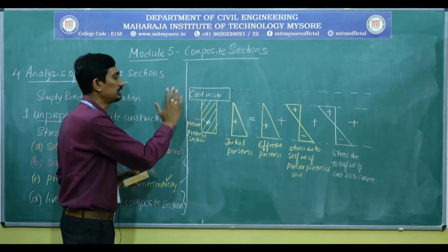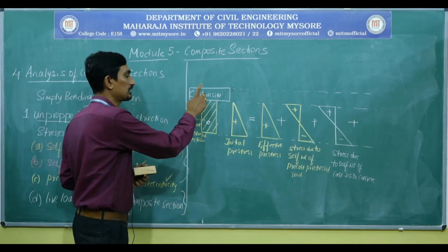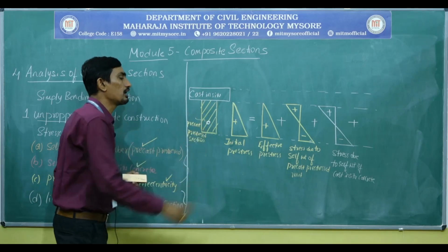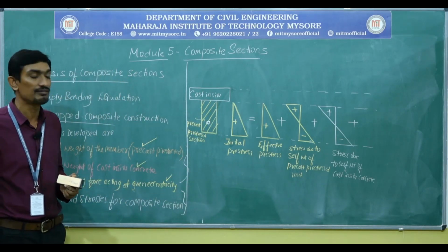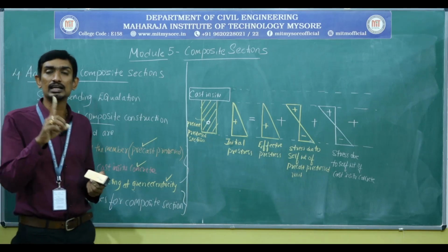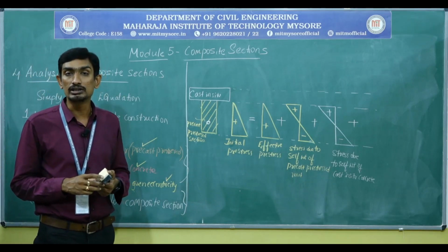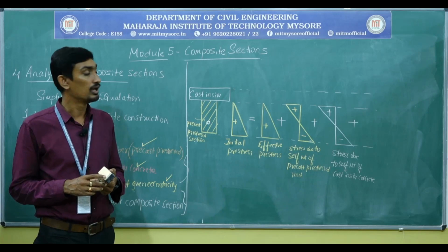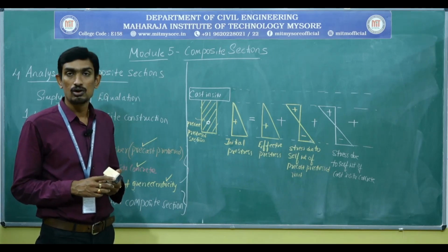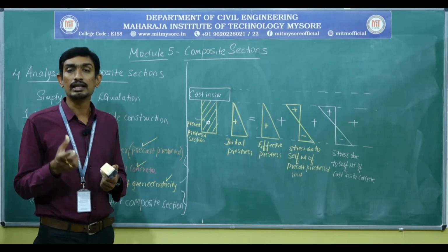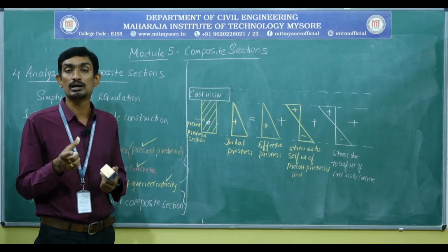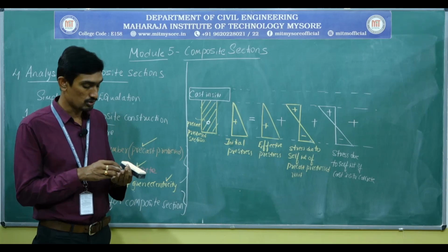So when I am going to cast this, the cast in situ concrete slab and the precast pre-stressed unit should structurally function as one single unit, or monolithic unit. So if it hardens, then the composite section will be subjected to the live load.